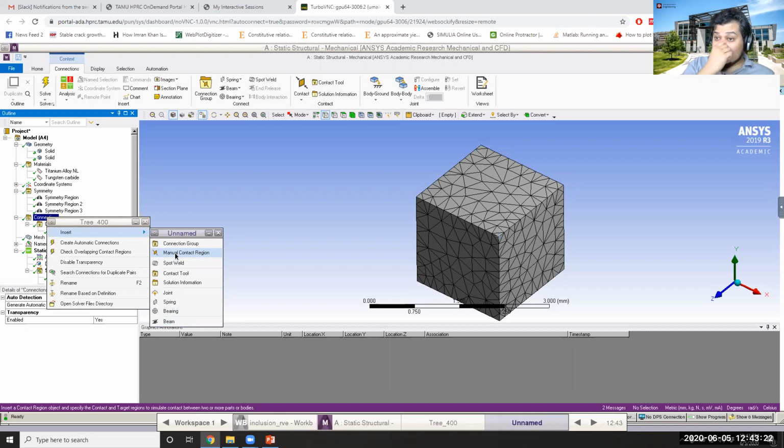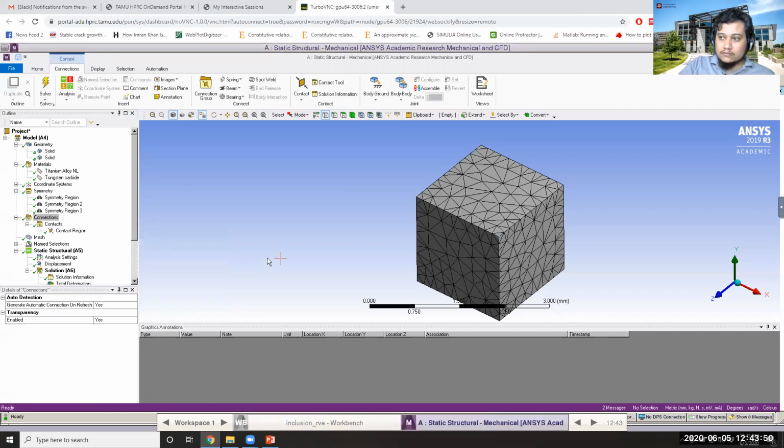But I strongly suggest that you try and create the geometry the way I did. Start with a single body, and then cut or slice the body there and there, so that these connections are made automatically for you. You can also do that explicitly using the options I told you. Does it answer your question?